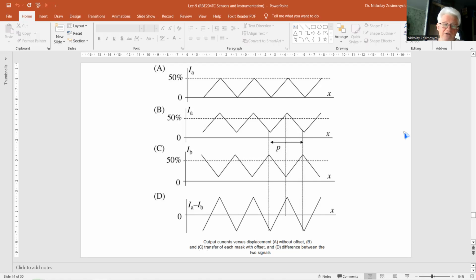It means half-pi phase differences, from which the electrical angle can be reconstructed, compared to the resolver signal processing in inductive and magnetic sensors. Another way is the arctangent method. The quotient of two quadrature signals is a tangential function. So by taking the arctangent of this function, the displacement is obtained. And obviously, errors in the amplitude, offset, and phase of these signals introduce position error.